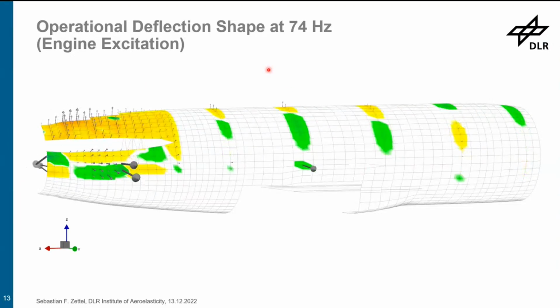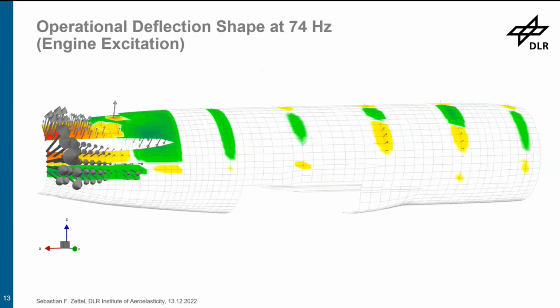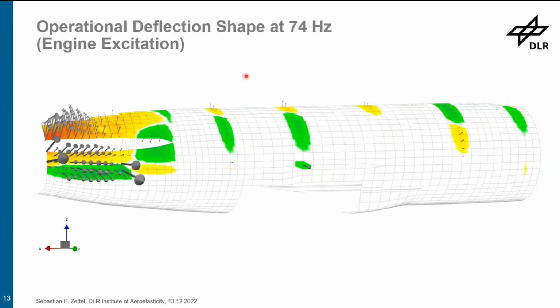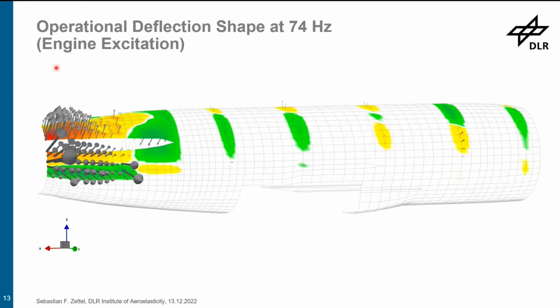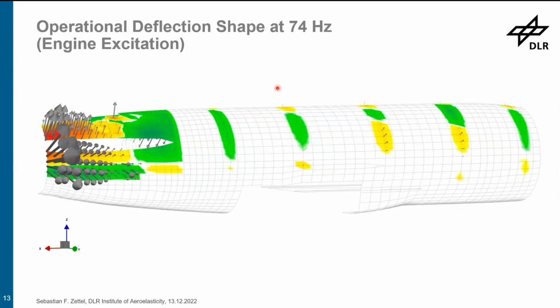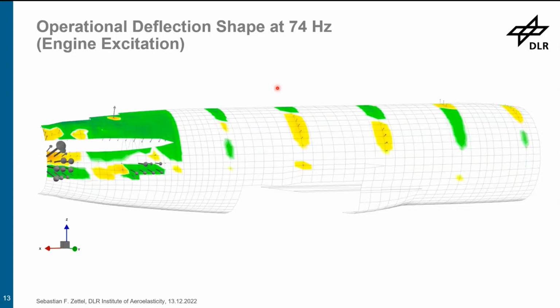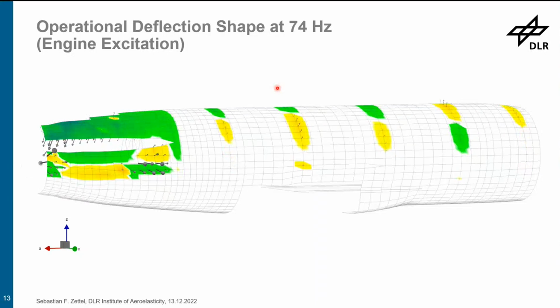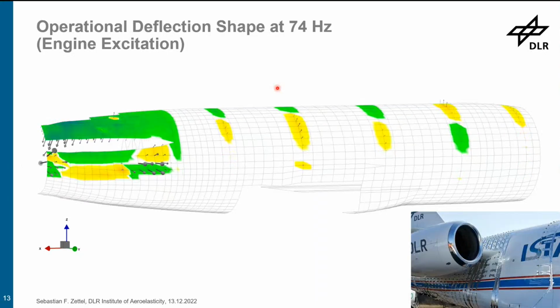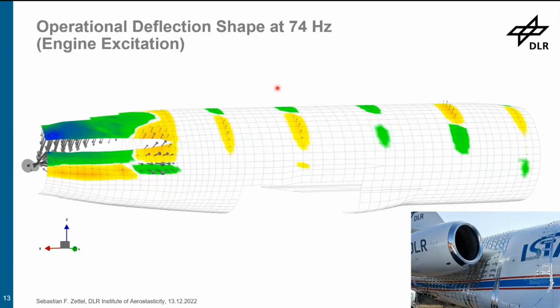Yeah, and we had some single sensors installed in the front just to capture the most important deflection shapes. The plan with this data is to apply the measurement data of the engine run onto an FEM model of the ISTAR, which will be updated in order to estimate the full structural behavior during the engine run. However, this model is not ready yet, so currently we use a workaround. Here I have the picture again for the sensors all located at the back of the aircraft.